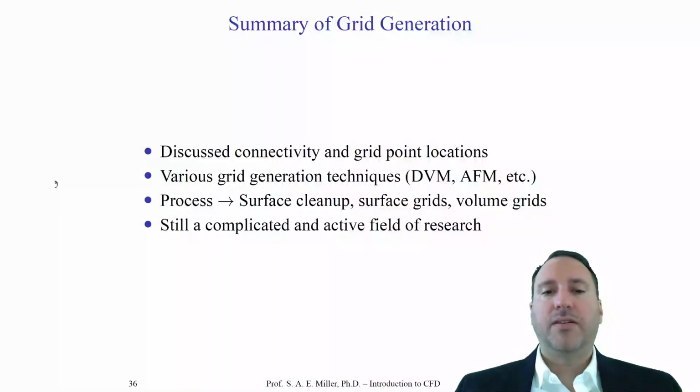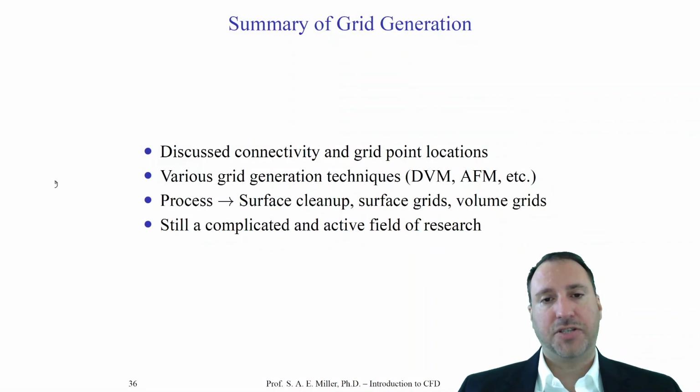We talked about 2 major techniques, the DVM technique and the AFM technique. Remember, this is the Delaunay-Voronoi method and advancing front method. The process is simple. We clean up the surfaces of a CAD model, for instance. That's the edges of the computational domain of the surface. We discretize particular lines that make up that surface mesh with grid points. Then we create surface grids on all the surfaces